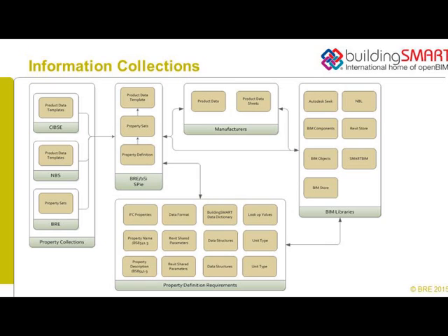There's one interesting thing about that, Paul, for parameters, whether you talk about countryfication, certainly something we found out in the work in Russia. Inbuilt parameters obey language tags. So if you fire up a Revit model in the Russian version and you use the built-in parameters, when you open that file in an English one and then save it out, all the inbuilt parameters change language. However, custom ones, anything you've added, don't.